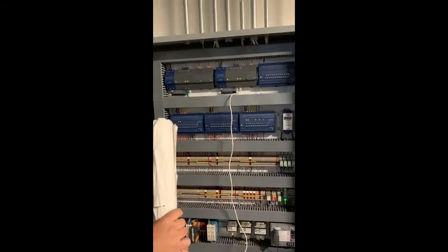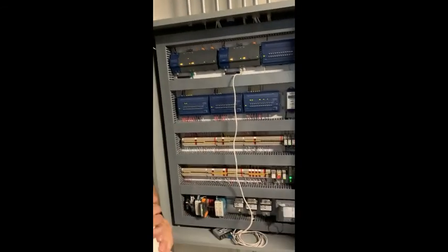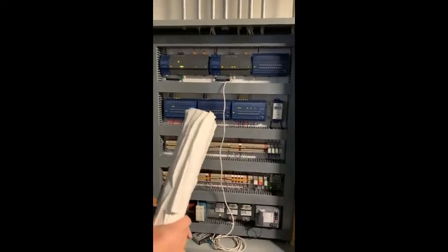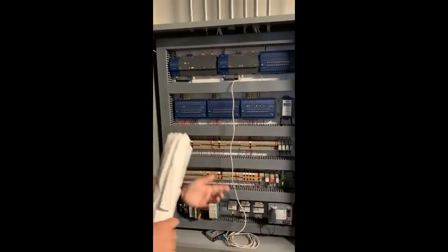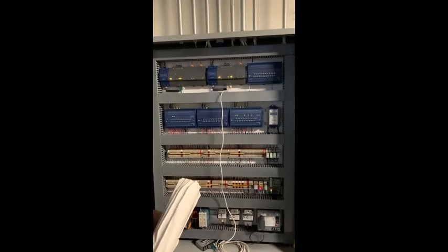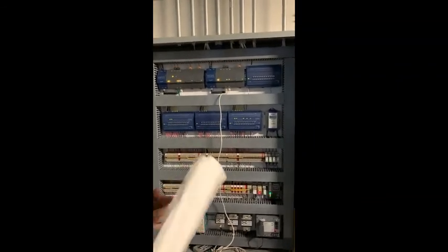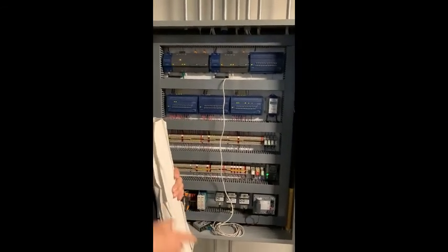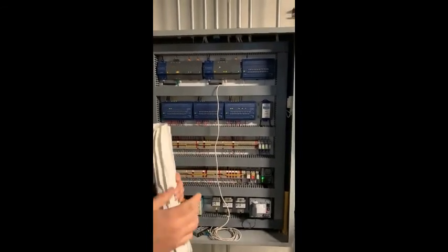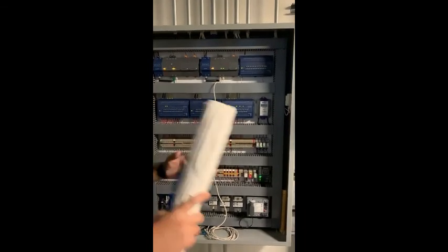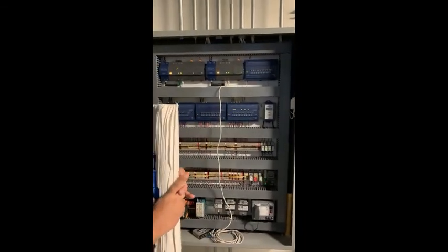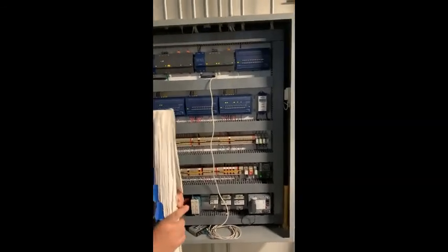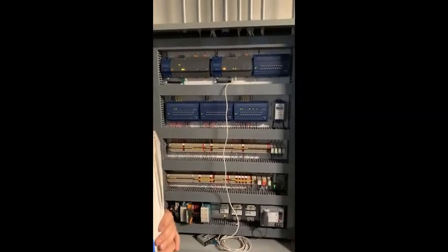We do have one Jace where we're doing a test for the manufacturer, where we remove the Jace and put in what they call an industrial PC in lieu of the Jace, because they're having some issues with the global points, and when we try to do some global points, some of the Jaces are acting up. So they wanted us to try actually taking the station out. So right now we have that in, and we're waiting to get answers from them about how we're going to move forward with it.